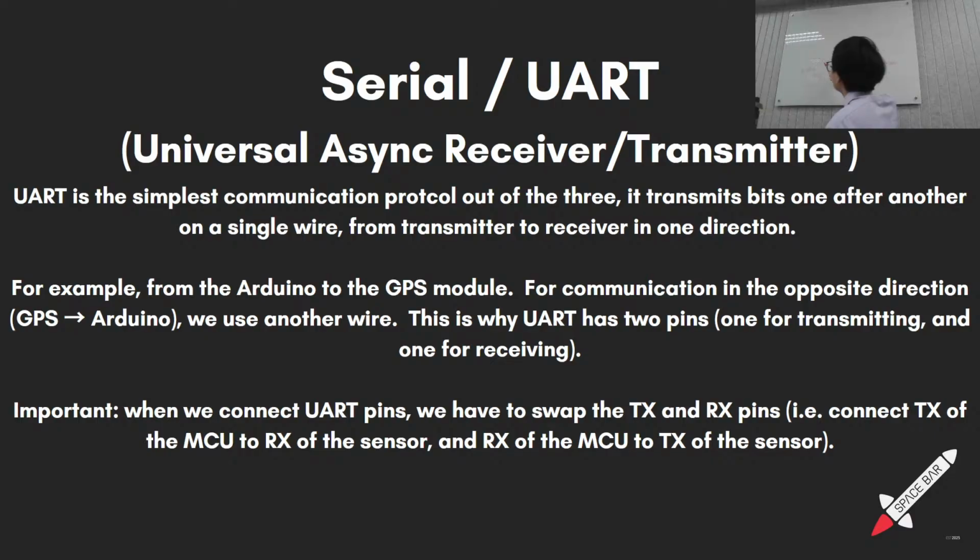Imagine I have 24-bit color on my RGB value for each pixel of my screen, 10,000 pixels, and each one has to have 24 bits, 8 bits each for R, G and B. It would take forever to send all that data using one line. No problem, I have 24 lines. I send you the entire pixel data at once. So parallel is great for stupidly high data rates, but we don't really use it for most things because the other stuff is usually good enough.